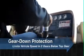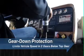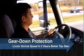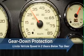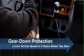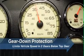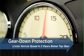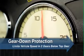The Gear Down Protection, or GDP feature, is designed to improve fuel economy by encouraging driving in top gear where fuel consumption is lower. This is done by limiting the vehicle speed in the two gears below the top gear, or 8th and 9th gear in a 10-speed, motivating the driver to upshift into top gear, reducing engine RPM and increasing fuel economy.